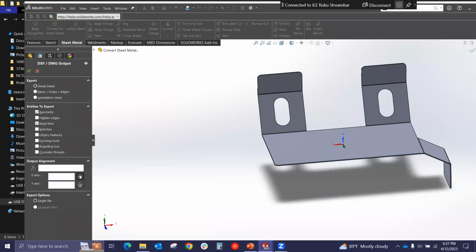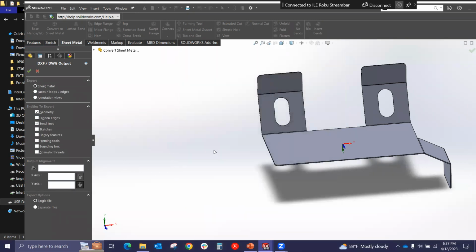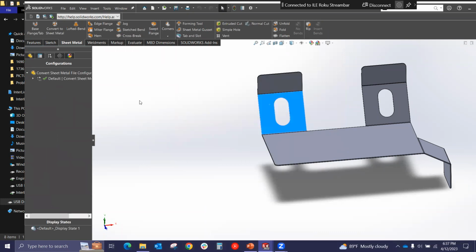Nope. And then you can also just create a little origin. How does it look in my drawing? I don't remember, but that's how I would go about exporting. I worked in companies where they just had a macro that automatically does it. The trouble with that is if you don't have it in the correct orientation on your model, then it'll export incorrectly, or you have the potential of exporting incorrectly.